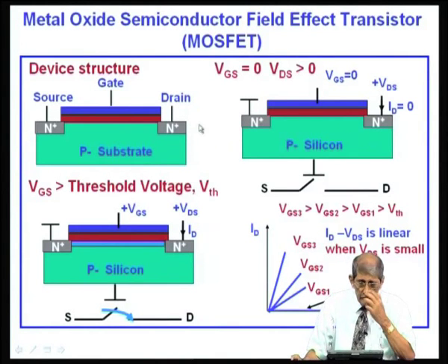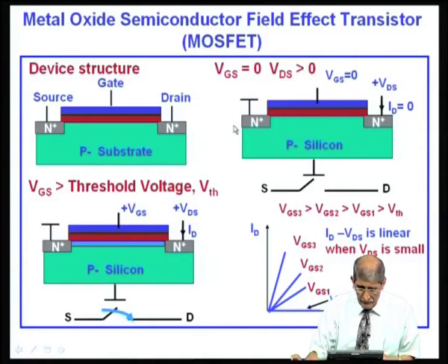Okay. Now, let us switch gears to another device, that is the MOSFET. The structure of the MOSFET, I have shown the cross section, exact cross section. This is the p type substrate, these two are the n plus regions. I am talking of one type of channel transistor called n channel MOSFET. This is the source, this is the drain, because this can supply electrons. If it can flow through this region and reaches here, it can collect this region, or it can drain those electrons which are reaching here.